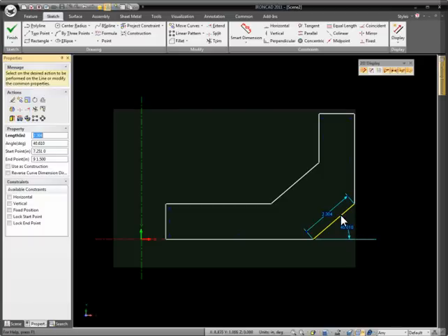Notice when I select this angle, I can drag this point and it gives me the ability to adjust its angle. And notice if you move slowly, it will snap to small 1-degree increments. When there's no smart snap appearing, you can see the 1-degree increments. When a smart snap appears, it's going to try to give you alignment to that. This is where it's handy to hold the shift key down to turn off those elements so you can get an exact value. For example, if we wanted 45, I'd hold the shift key down, get to the 45, and release my mouse.